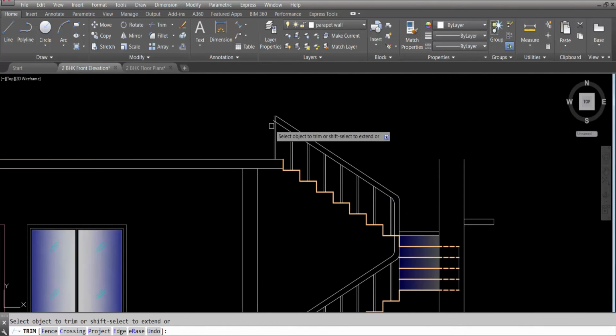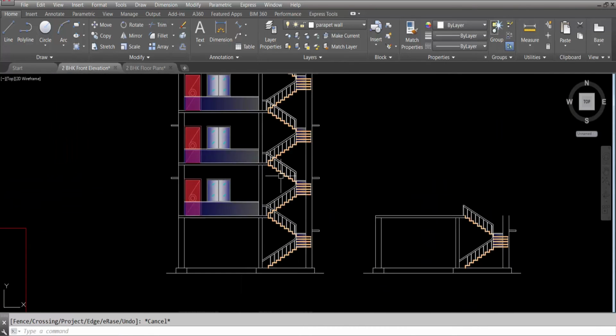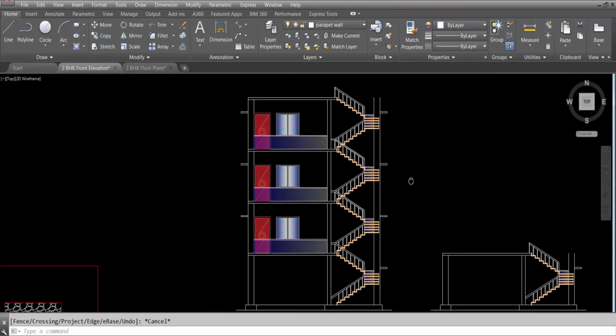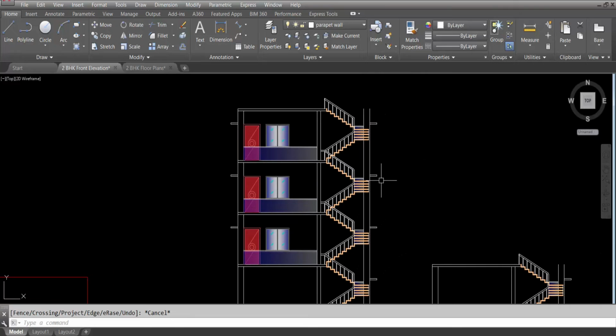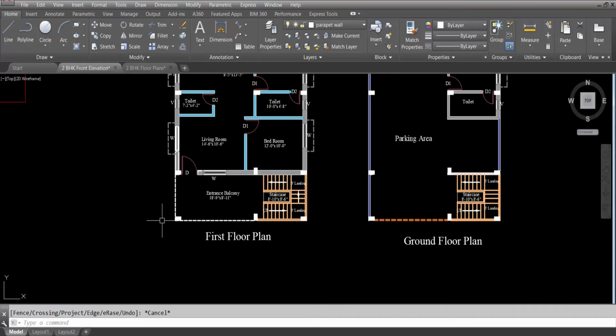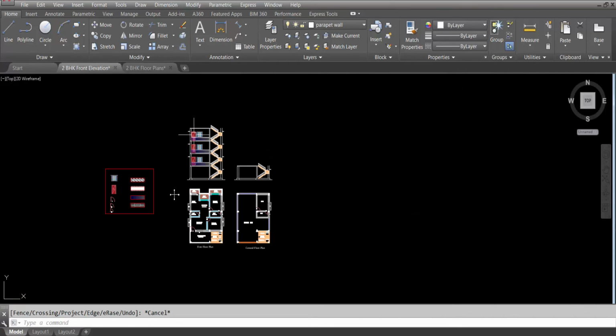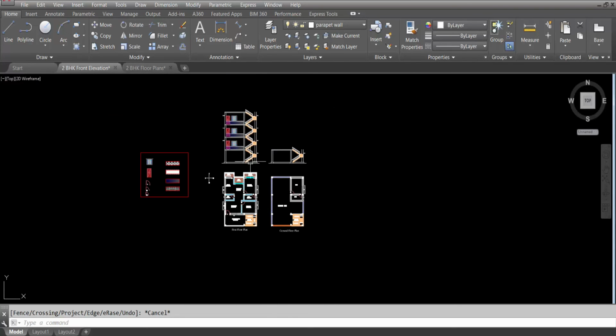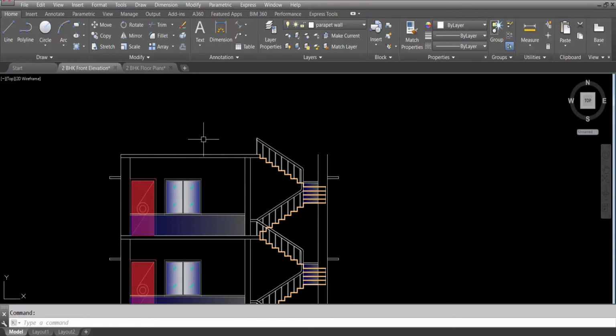See, you have to do this properly. You have to do it properly, because when you convert this AutoCAD file into Revit, you cannot create the 3D view properly. So you have to create everything as per layer. Okay, here the whole parapet wall will be there in the last terrace. The terrace parapet wall will be here, and here on this side after the staircase, the headroom. This is not headroom, only the roof slab will be there.